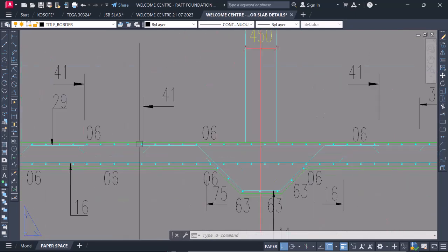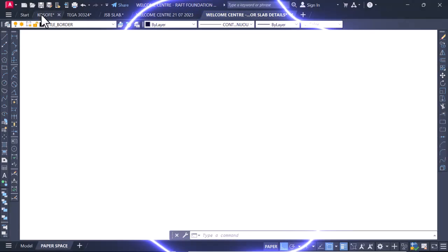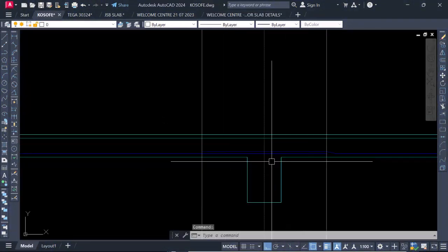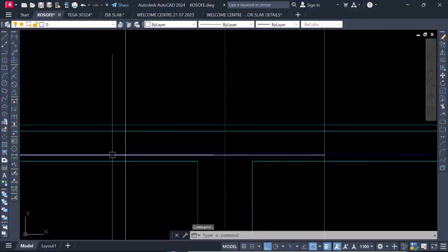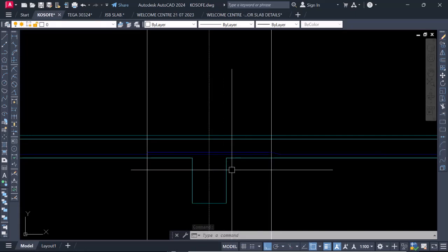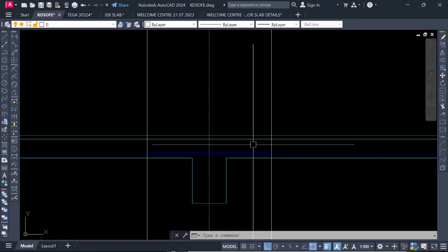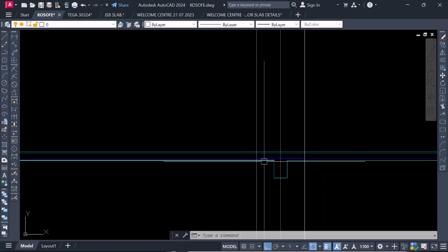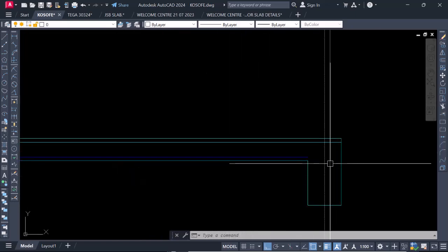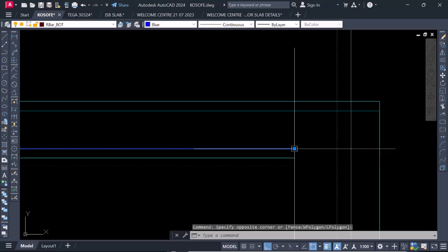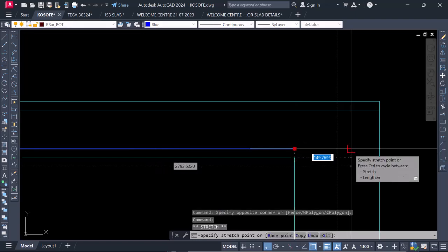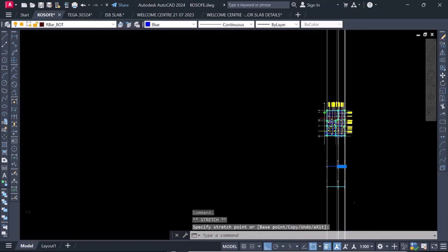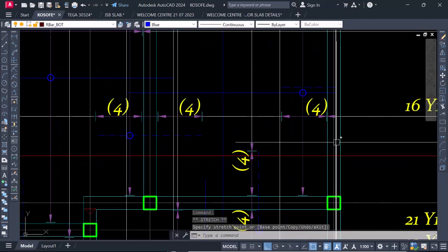Otherwise, if you don't want to use the kink, you can as well go back to use our overlap reinforcement. You can do this. You can see this is actually proper, right? So in doing this, we can still go back. Currently we're done with this, and we've gotten to the end of this. What we're going to do is extend our rebar from here down to meet where it starts along here that we picked.